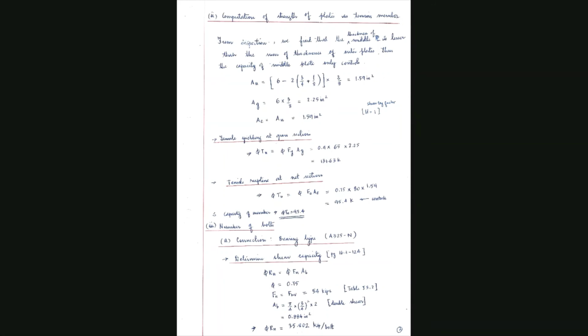If your problem had only just two plates and a bolt in them, this value would be 1. But in this problem, we have three plates. The middle plate is being pulled on one side, while the other two plates are being pulled to the other side. The same bolt is subjected to two planes of shear.